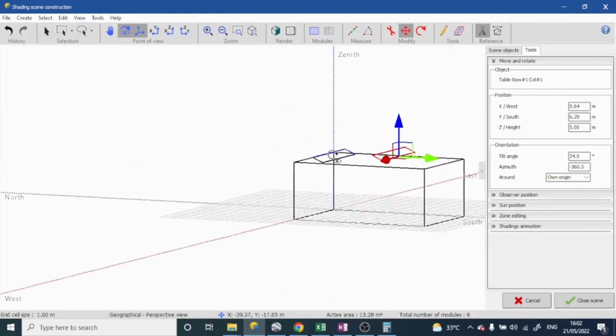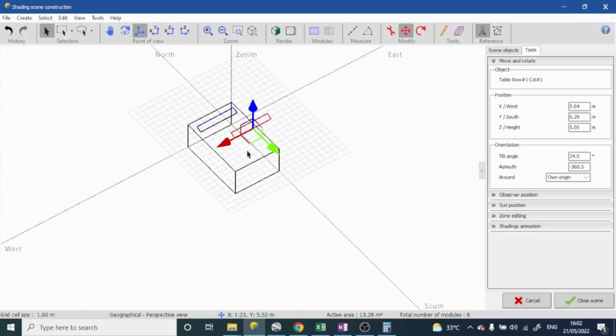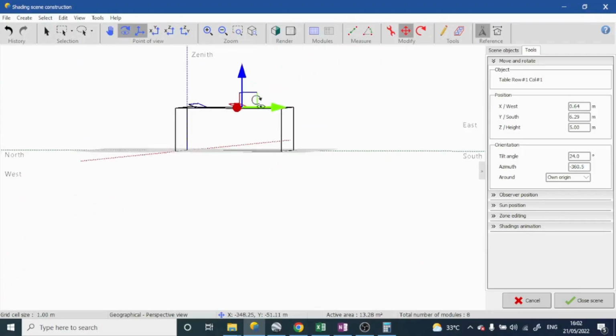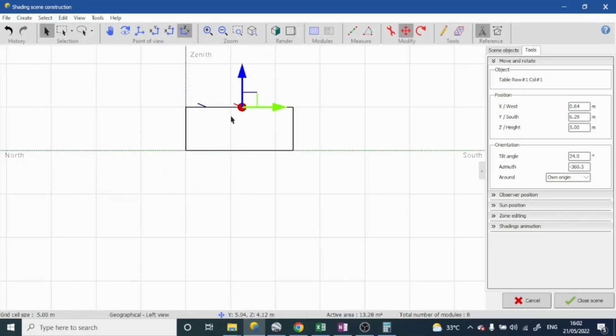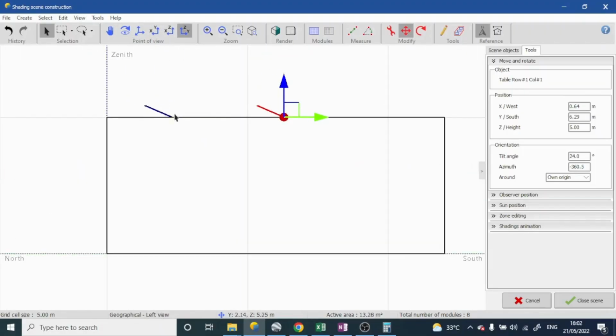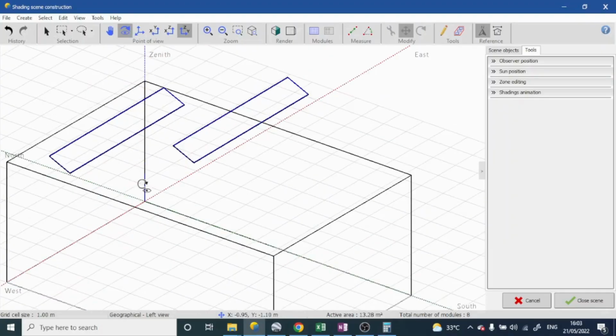But a higher distance could be possible here. The available area is not allowing for shooting purposes or moving purposes. So we try to reduce the inter-row spacing in that case. So we just keep it as 3 meter. So this is the 2 meter of an area that we can say, and we try to reduce up to 5.29 distance like this. So now the inter-row spacing that we had, we can reduce.